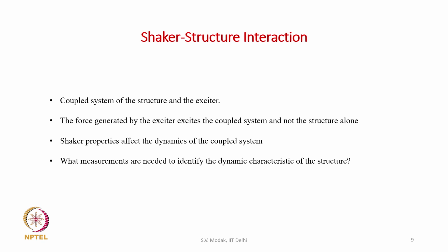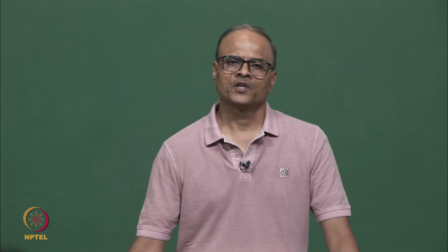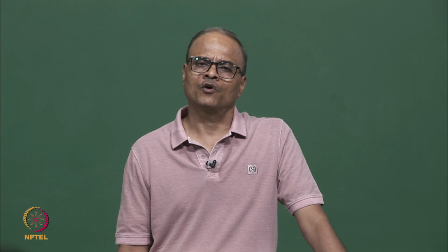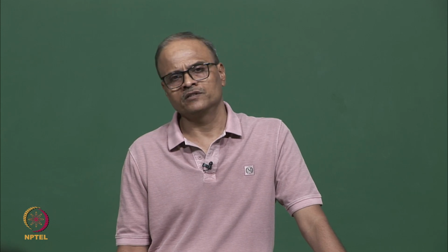So, what we are going to do now is take a lumped parameter model of the shaker structure system, and then determine the FRFs between various inputs and outputs, and study them to see which particular FRF leads to the correct estimate of the dynamic characteristics of the structure.